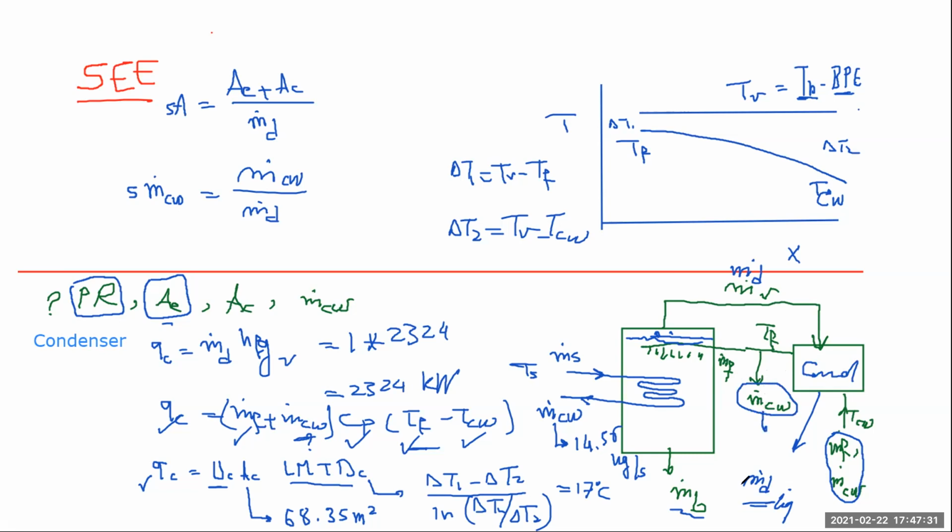This is a waste. At this temperature, we can use it for another single stage unit, or maybe an HDH unit or a membrane distillation unit, so I can make use of this water and not throw it away. The same thing applies here. You are rejecting 1.5 kilogram per second of brine to the ocean again at a temperature of 75. That's another loss. And this is why the idea of having the multi-effect desalination came from.